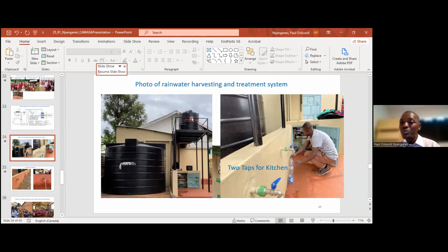And this tank should not be so huge, such that we don't need to store the water there for a long time. Because again, we may have some particles inside. It's just to use for that day and that is it. And then collect overnight and then tomorrow again there's water because it is continuous. So we have to ensure this tank is not huge. The one which we need to ensure it is big enough to collect the water is the first tank to have storage.